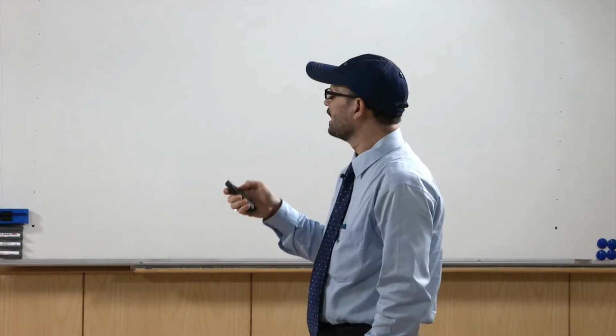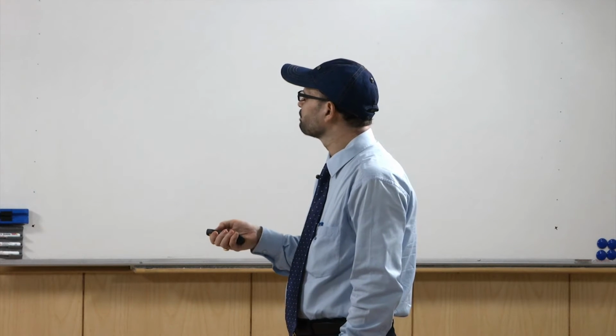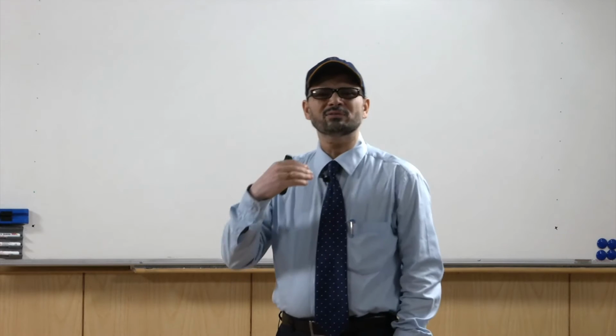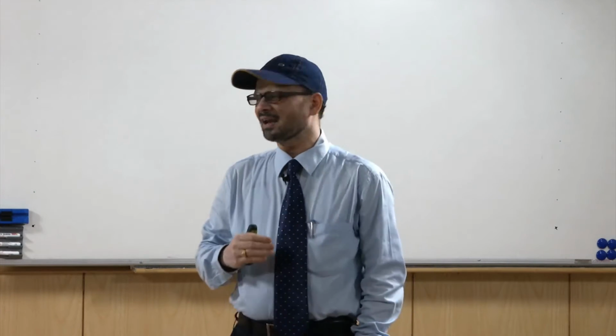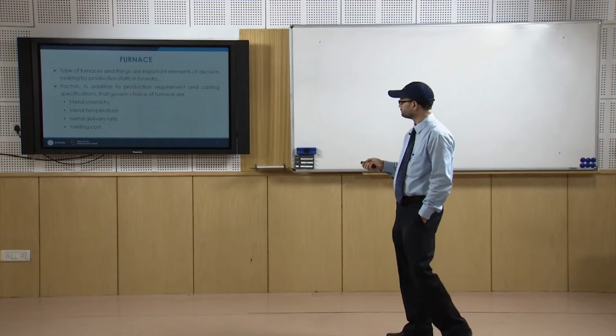All these things are important to be considered. What will be the slag composition, and how is it going to react with the lining? These are important parameters when we choose a particular furnace.